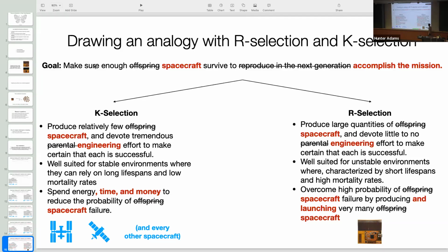So as long as we understand the statistics of failure, we can do the back of the envelope calculations to say, okay, if mission success requires that I have X number of chipsats alive after Y number of days, and if I have a certain probability of failure per day, we can solve for the amount that we need to launch. And it might be a huge number, and in the case of chipsats, that's okay.